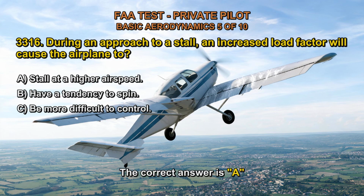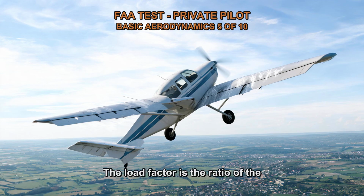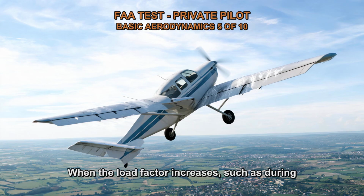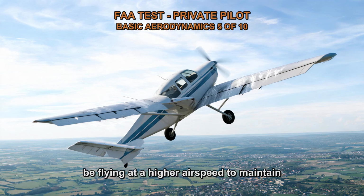The correct answer is A. During an approach to a stall, an increased load factor will cause the airplane to stall at a higher airspeed. The load factor is the ratio of the lift force acting on the airplane to its weight. When the load factor increases, such as during a steep turn or a pull-up maneuver, the stall speed of the airplane also increases. This means that the airplane will need to be flying at a higher airspeed to maintain lift and avoid stalling.